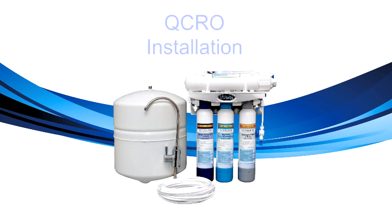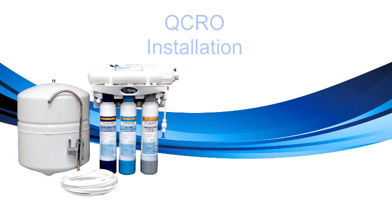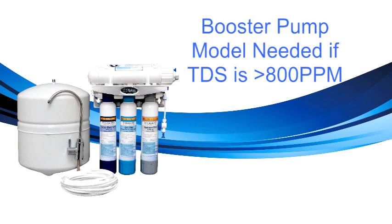Before installing the reverse osmosis system, you need to evaluate the limitations of the system and determine the proper place to locate the unit. QCRO systems should not be used on water systems that are microbiologically unsafe to drink or with a total dissolved solids level in excess of 800 parts per million. For water with a higher level, Sterling offers RO systems with booster pumps.